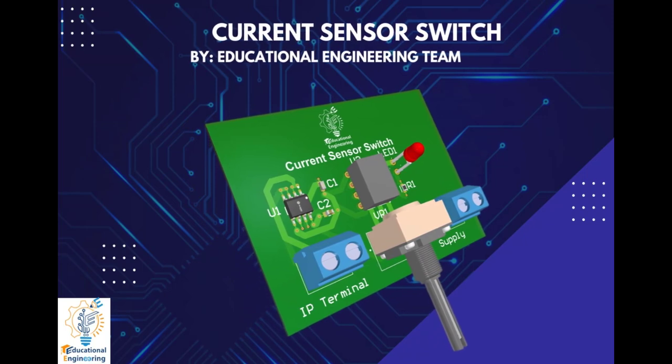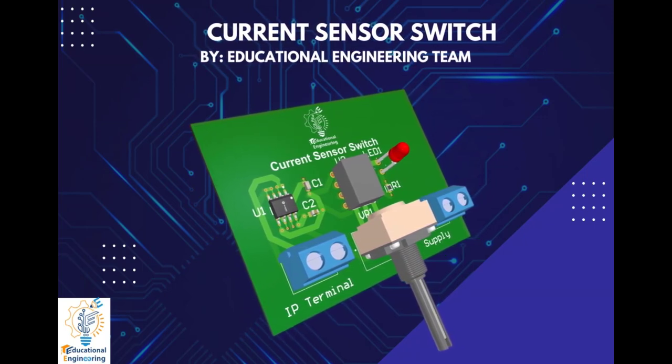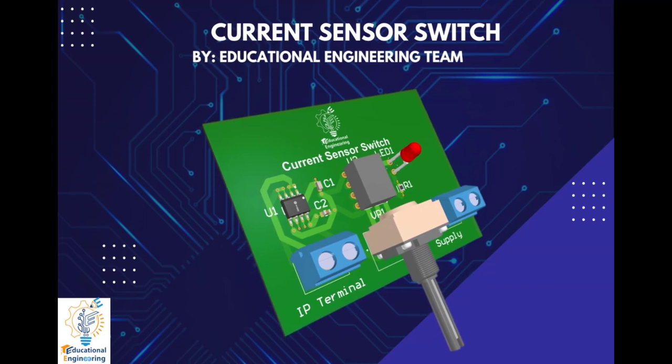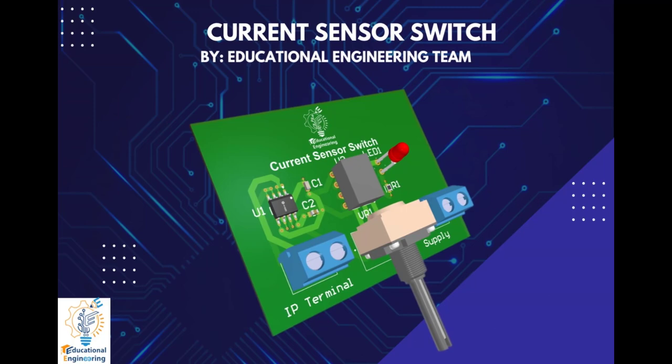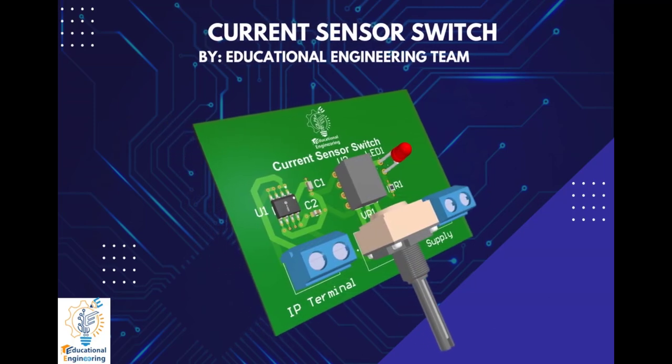The IC is a low-cost Hall effect current sensor which is capable of measuring current up to 20 amperes. This IC consists of a copper conduction path through which the current to be measured flows. The output voltage will be proportional to the input current flow. Also, the output voltage of this IC will change by 100 mV per ampere.